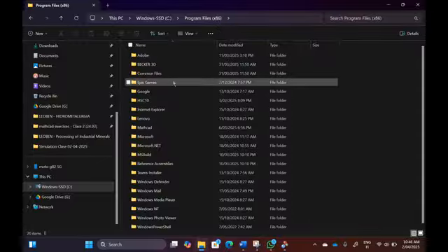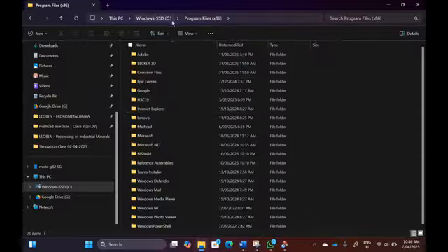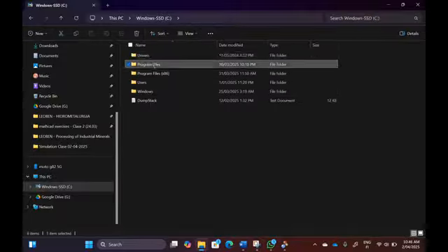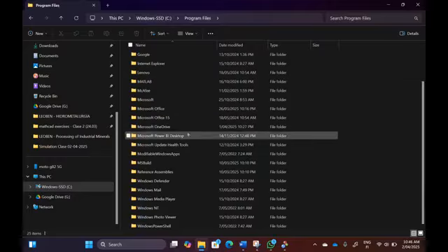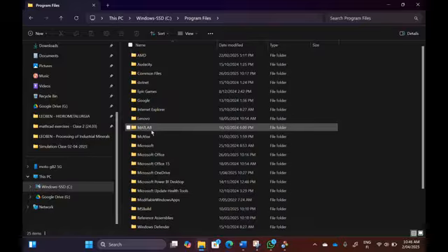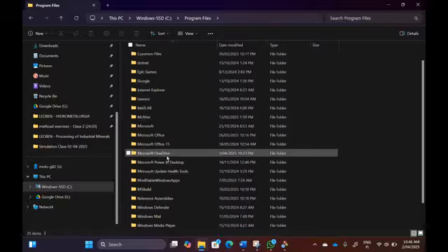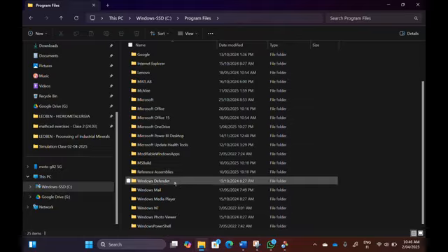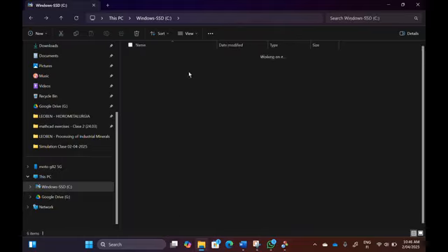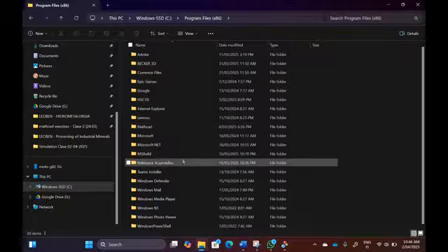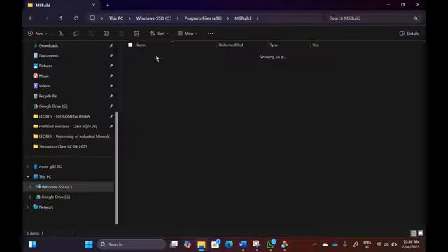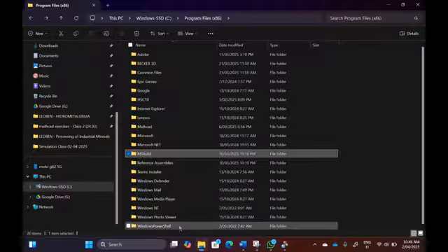So everything, like you see here: add material, iron ore, set material, density 3750, and so on. It's a very long script. Material is relatively long, and you can import them. So far, so good. Now, transfer the INP file from your install folder and put it in your working directory.